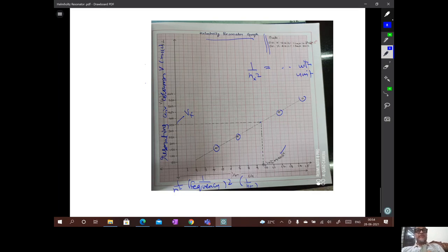What else do you want? Vs. So the frequency is equal to Vs, the sound velocity in air, divided by 2 pi, times the square root of A over V L. L is the neck length. You can calculate it again by using a scale. It's an approximate value, no problem. Then you can calculate the volume. Assume that this is cylindrical, calculate the area here and multiply by the length, and you will get the volume. So you can calculate the frequency.